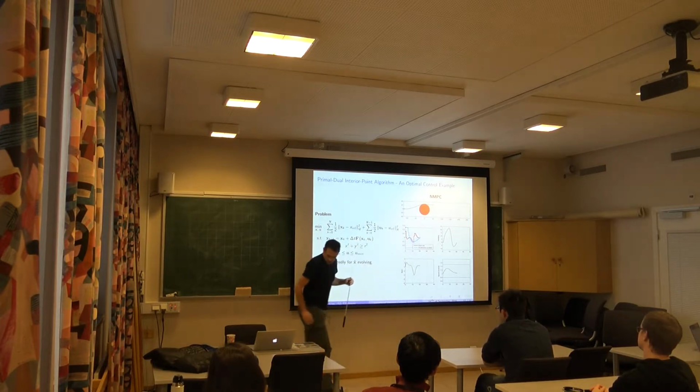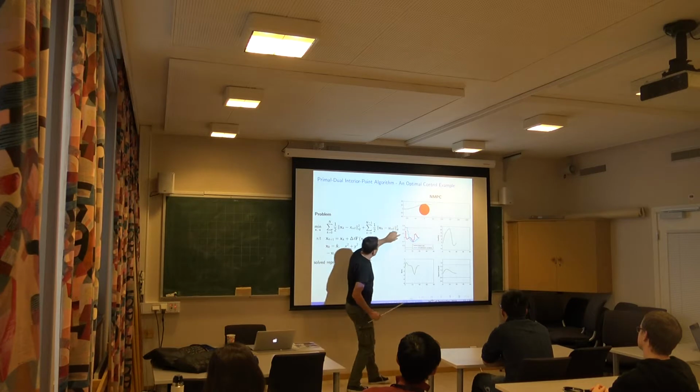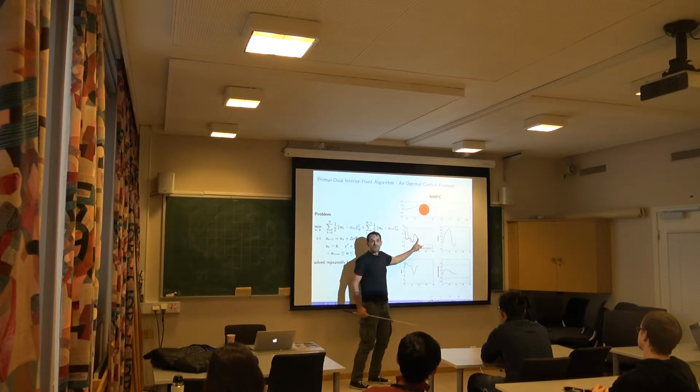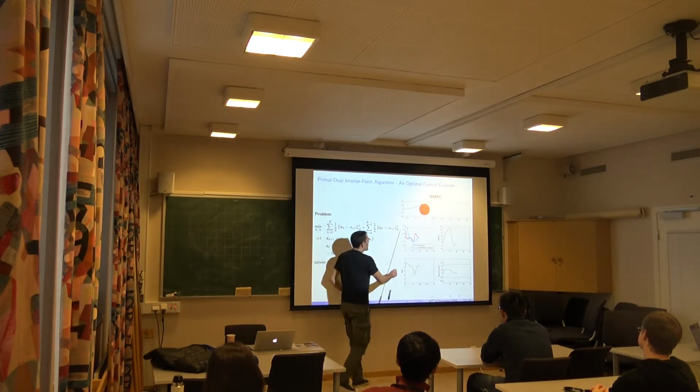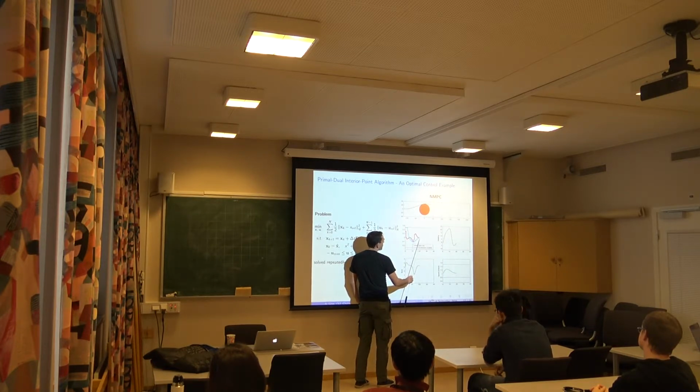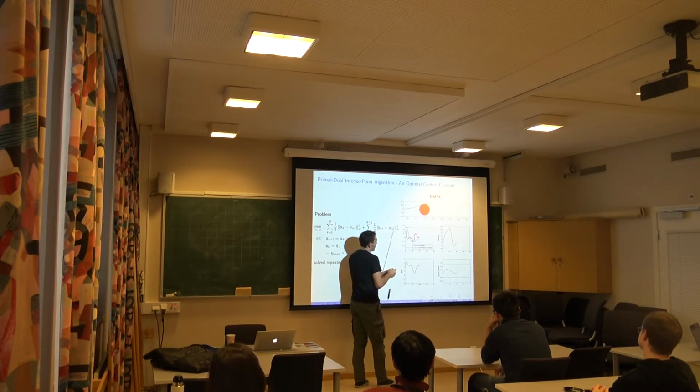If you look at the solutions, not much really happened. So if I could start my problem from the second sampling time and use these guys as solutions all the way to N-1, skipping one timestamp, they would be close to optimum. Does it make sense? So once you've solved a problem once, the next problem is very similar to the one before. You need to fill one timestamp at the end, so decide what will come at the last time instant, because you don't have it yet. But you can make pretty good guesses about that. So that's one source of changing the solution a bit.